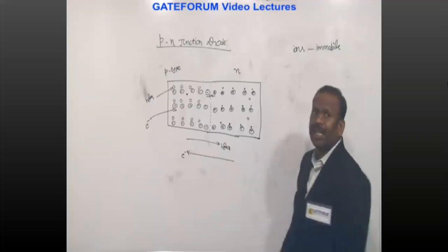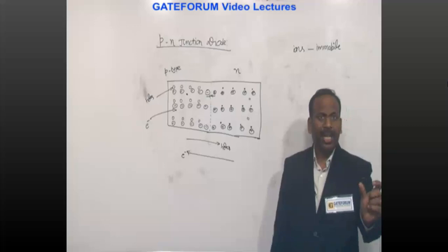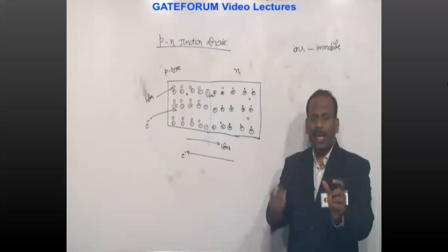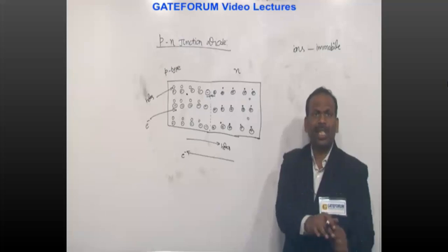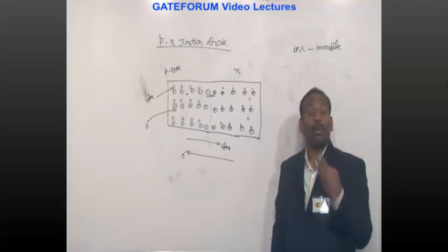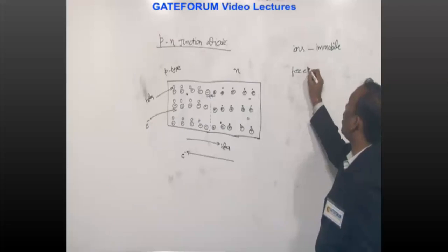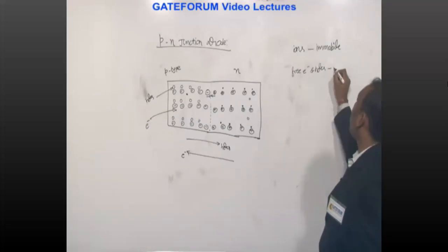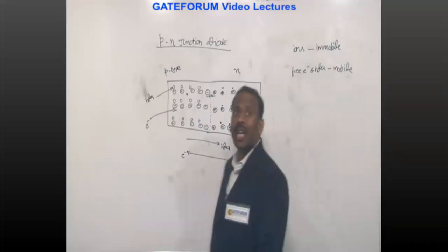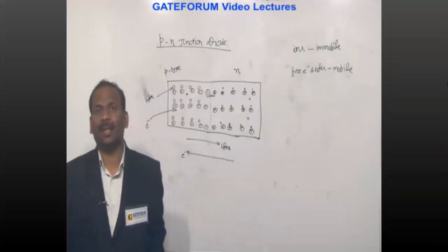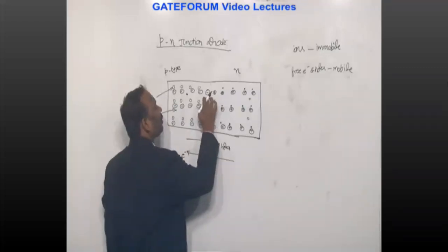Ions are immobile means they will not move from their position. The nucleus force is there; it donates or accepts one electron and becomes an ion. It will stay in that position, it will not move. Then who is going to move? Free electrons and holes are mobile charge carriers. Current is always due to mobile charge carriers, not due to immobile ions. Therefore, this is not going to happen.